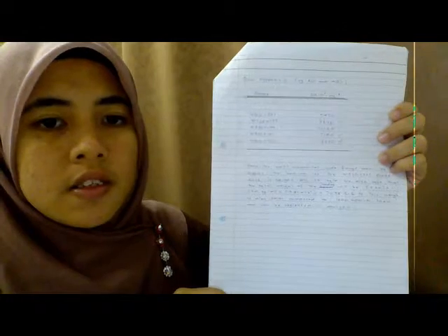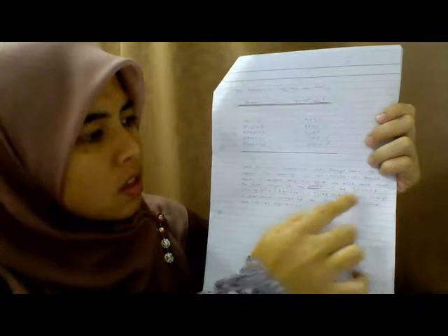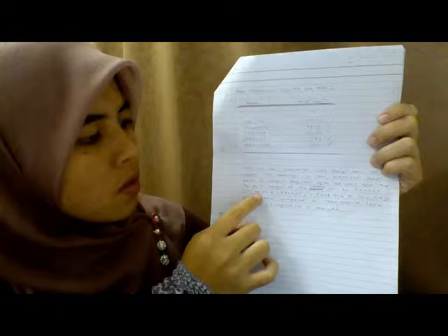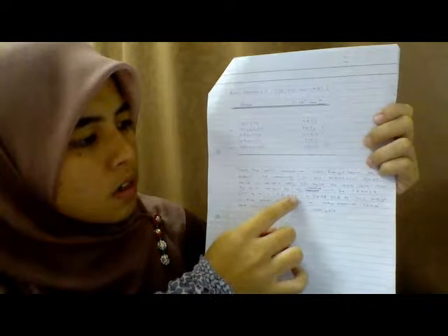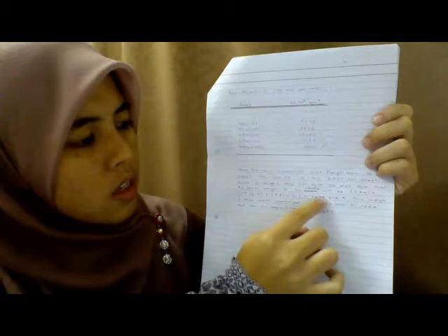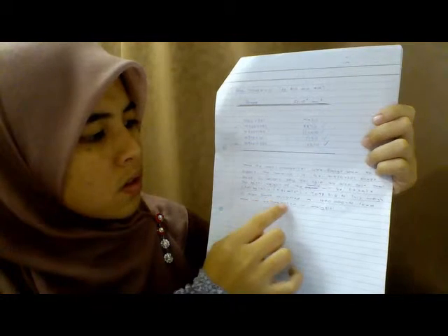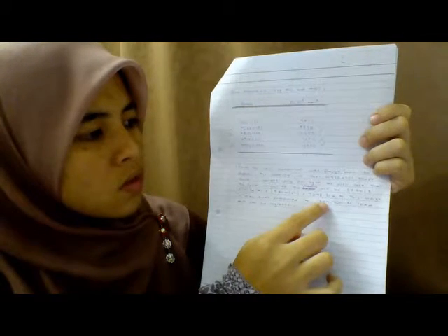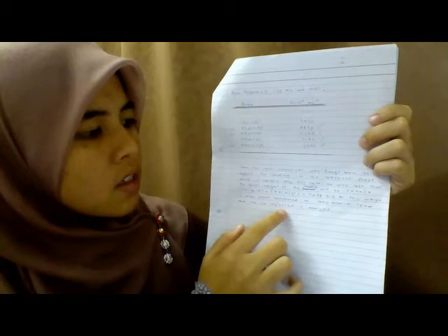This is because we also noted that the total weight of the beam will be 3.6 meter times 201 kilogram per meter times 9.81 meter per second squared, which is equal to 7,088.516 Newton. This weight is also small compared to the 160000 Newton load, and it can be neglected in the analysis.